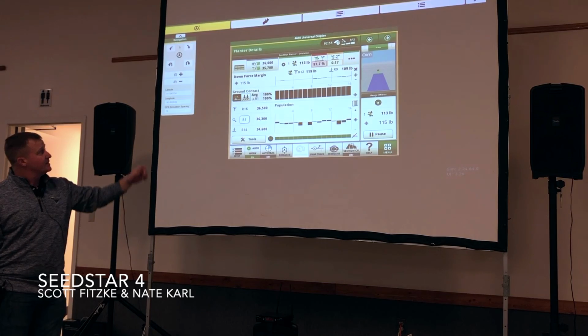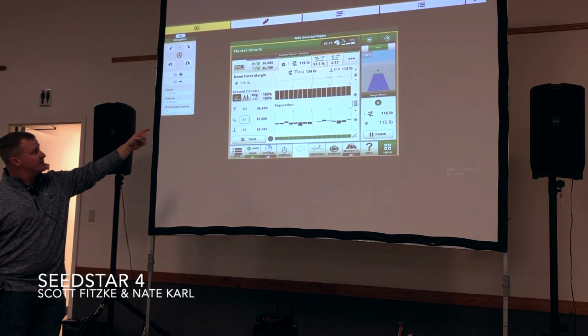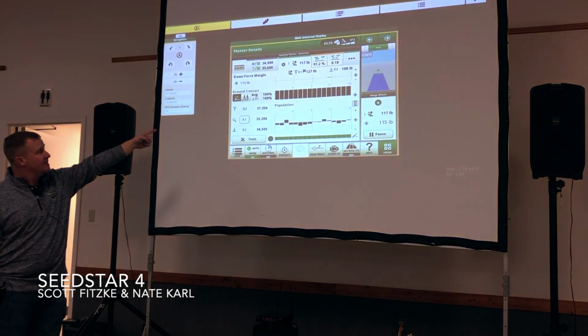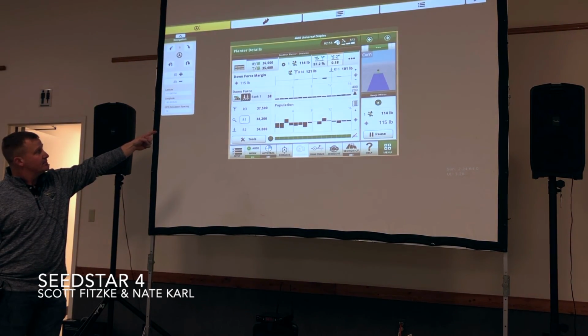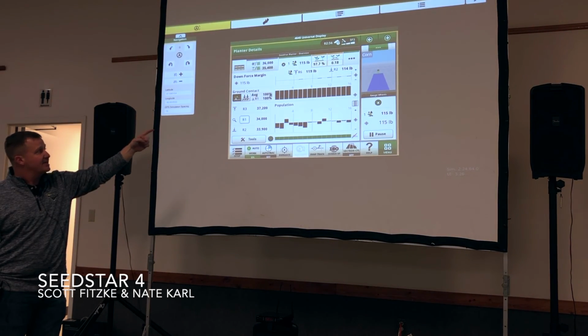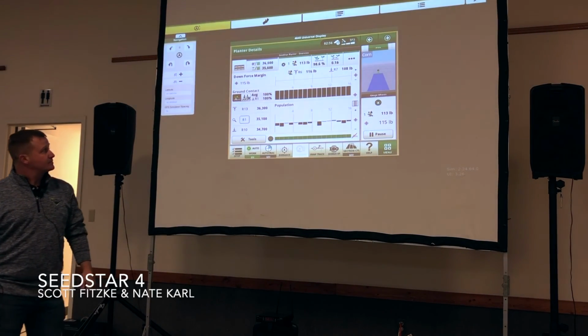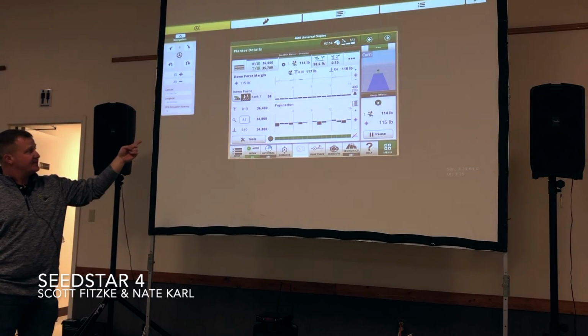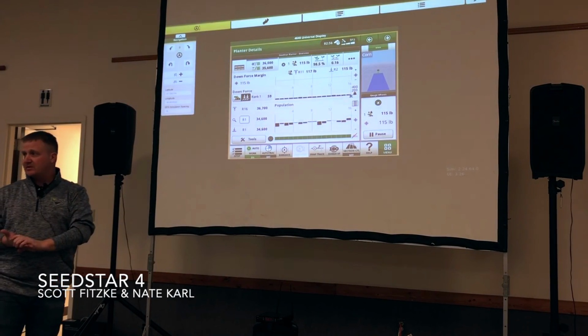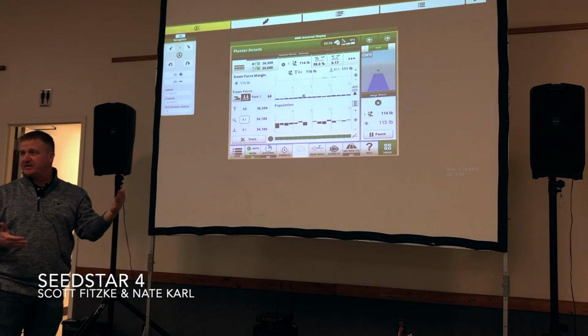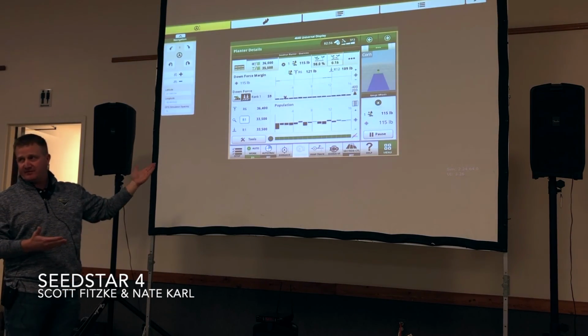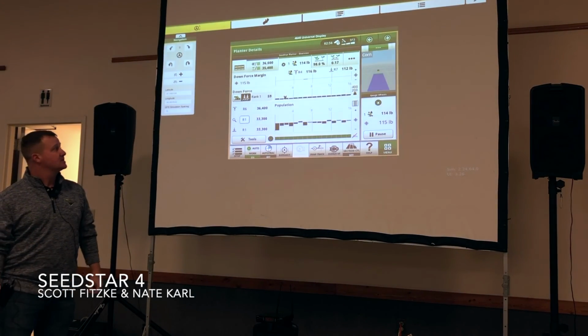Okay. Next box going down, go back and gauge wheels. Your ground contact right there. And that's your ground contact, that's how much you're holding it on the ground. So you want that obviously to be as high as possible. That next box there is your actual downforce. So again, the old way of looking at it, if you had 300 pounds on it, that would be the reading, even though you're only getting 115 pounds of margin.